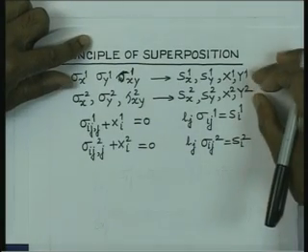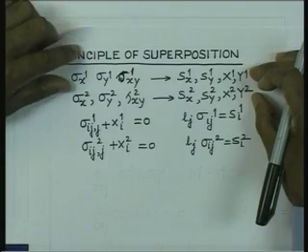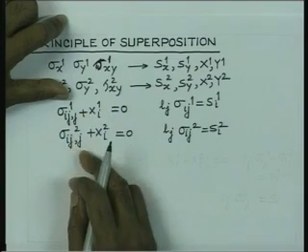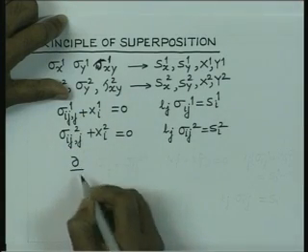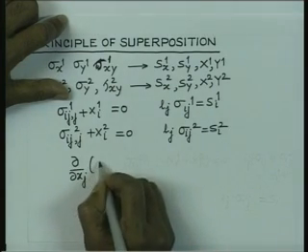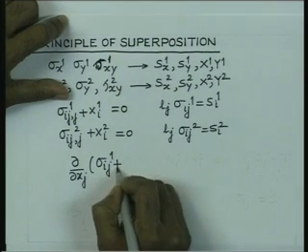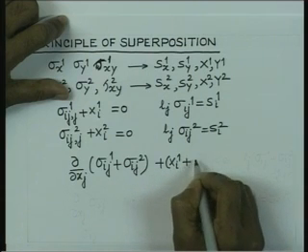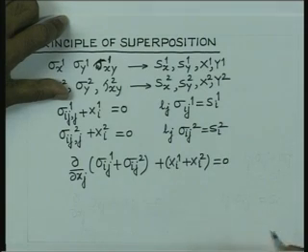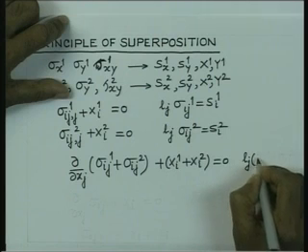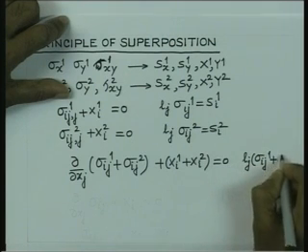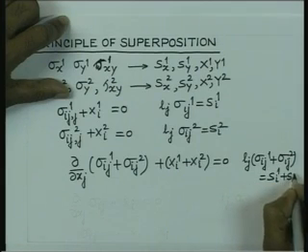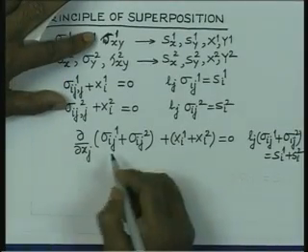Now, if we apply the two sets of loading together, then the stresses can be directly added and we get the total stresses. This can be shown like this: if we add the two sets of equations, then we are going to get ∂/∂xj of (σij(1) plus σij(2)) plus Xi(1) plus Xi(2) is equal to 0, and similarly if we add the tractions we get lj (σij(1) plus σij(2)) is equal to Si(1) plus Si(2).